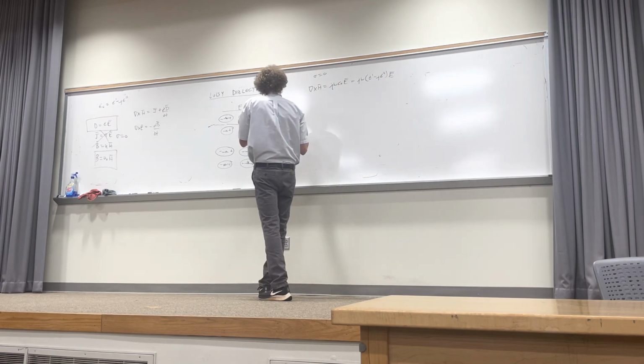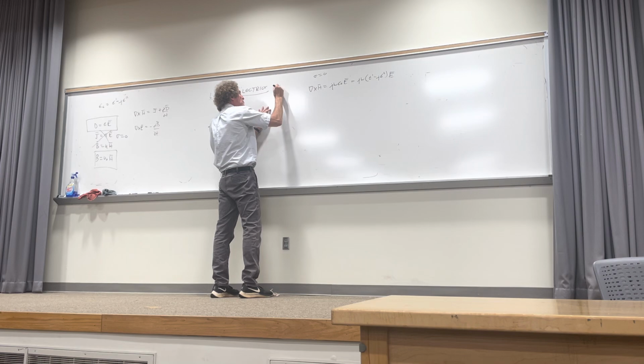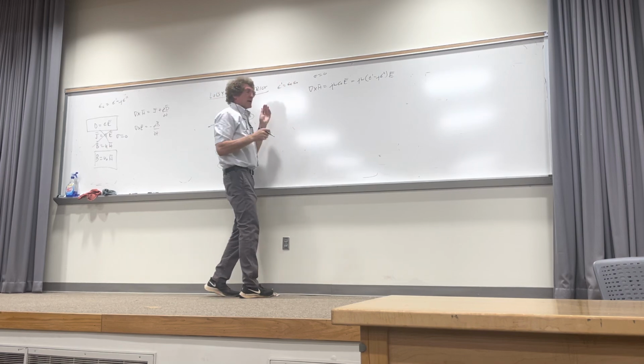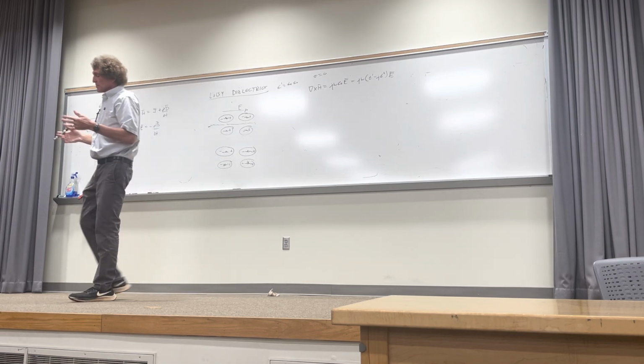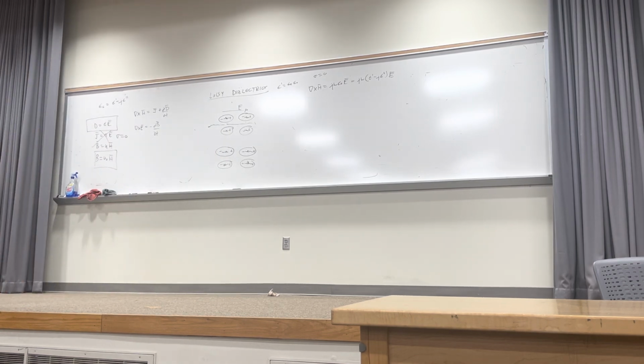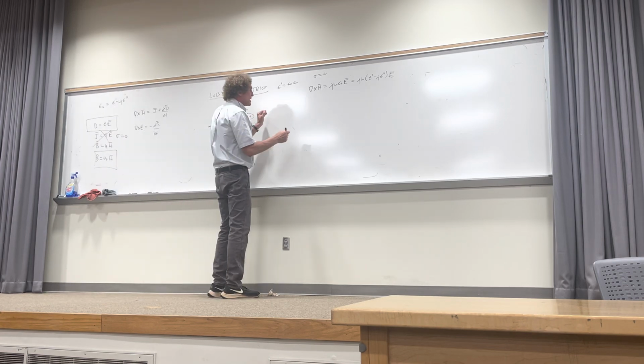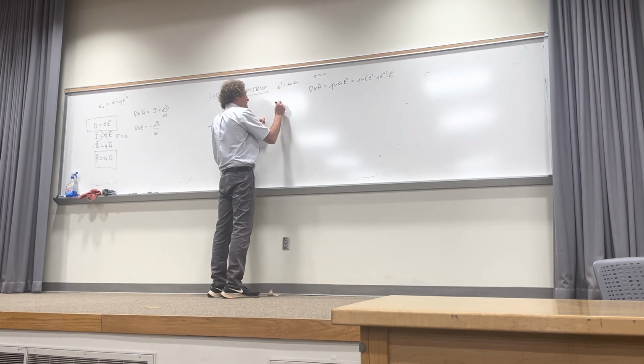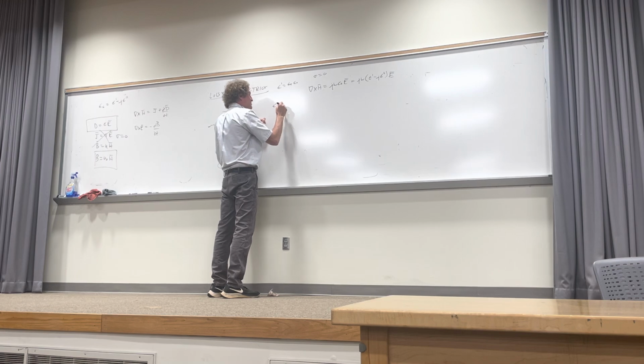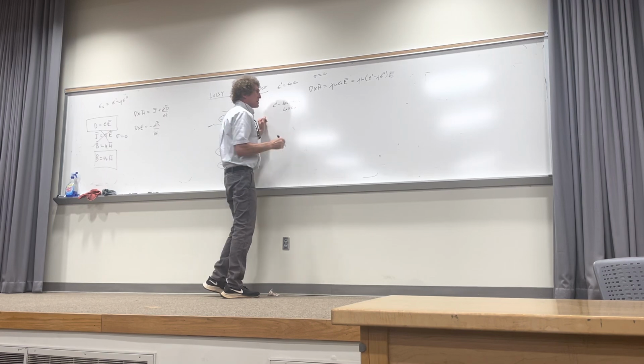Okay. Now make a note of this. Epsilon prime is just equal to epsilon relative epsilon naught. That's the old epsilon relative epsilon naught that would be there if you were at 0 hertz, if there was no frequency variation. Y'all follow me on that? This second term, epsilon double prime, has to do with dielectric losses. I'm going to go over here.